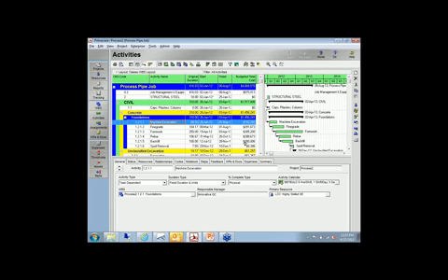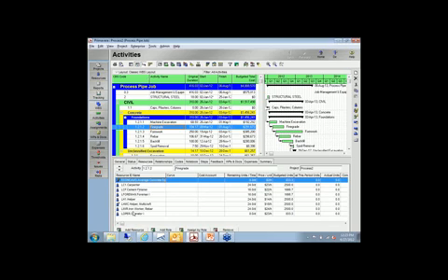So Hard Dollar loaded the Primavera schedule with all of these costs, and if we were to drill down into an item, let's say fine grade, you will see in the resources section that Hard Dollar also resource loaded the schedule. All of these work hours came in from the Hard Dollar estimate. So if we make a change to the estimate, maybe use a different group of resources to do this fine grading, those will flow into Primavera automatically. We don't have to worry about manually resource loading the schedule.